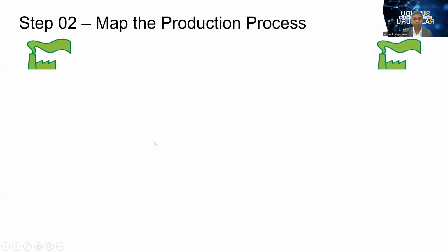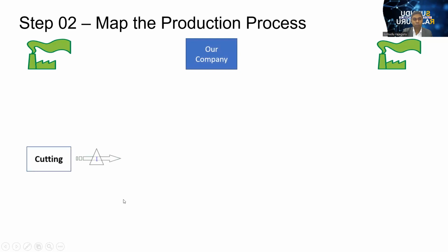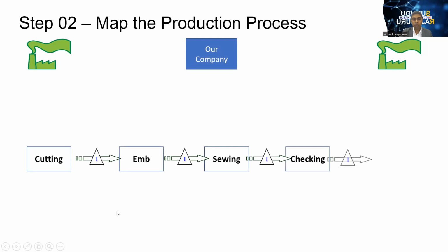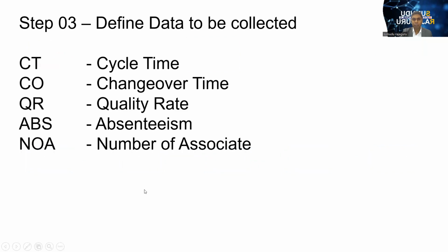Customer, supplier, then our company, then our process flow. Don't think of anything complex. Each process we have to connect through an arrow. Usually this arrow should be a push arrow, because when we draw the first current value stream map, almost all places have some WIP inventories. I denote those inventories with a triangle, then connect through the push arrow.